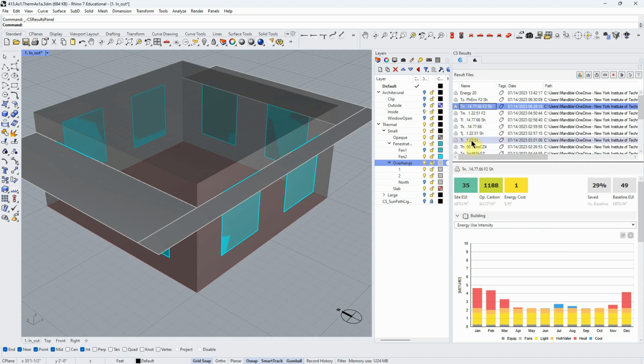So compared to the original low solar heat gain, we got the high solar heat gain with a little bit higher U value, like 30% higher U value, and shading is our best setup so far in terms of EUI, the total amount of energy we're using. We basically got rid of our cooling load, though. I think down here we got rid of it even more so. Maybe here? Nope, that one even had more. Anyway, we were pretty successful in getting rid of that cooling load.